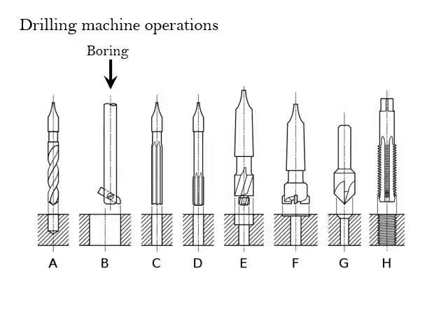Suppose 25 mm is required. Nearer to that, first make a hole on that component, 24 mm. Then 1 mm of material is removed from this component. It is called the boring operation. Clear this point.